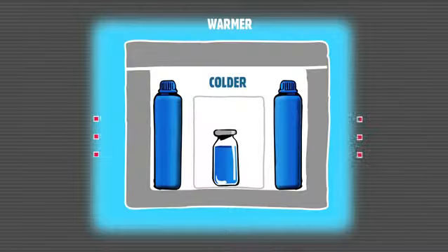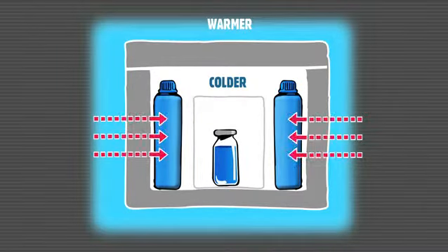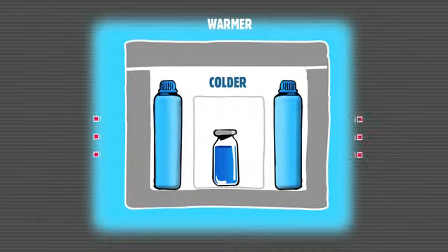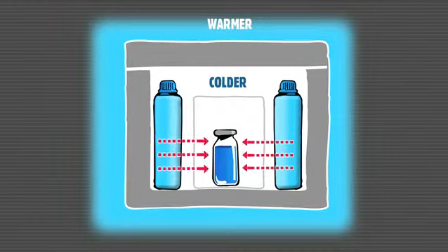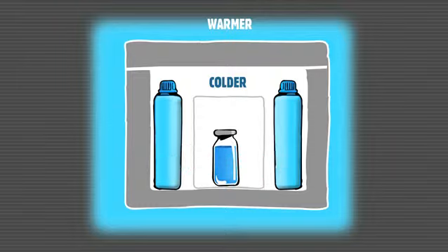For instance, if we design our package to meet a certain amount of total heat during distribution, and that heat is exceeded, as that heat enters the package, it's absorbed by the refrigerants. If it's too long in that environment, an equilibrium will occur inside that package, and eventually the inside of the package is going to attain the same temperature as the outside of the package, because all of the energy that we had stored up in our capacitors, our refrigerants, has been used up.